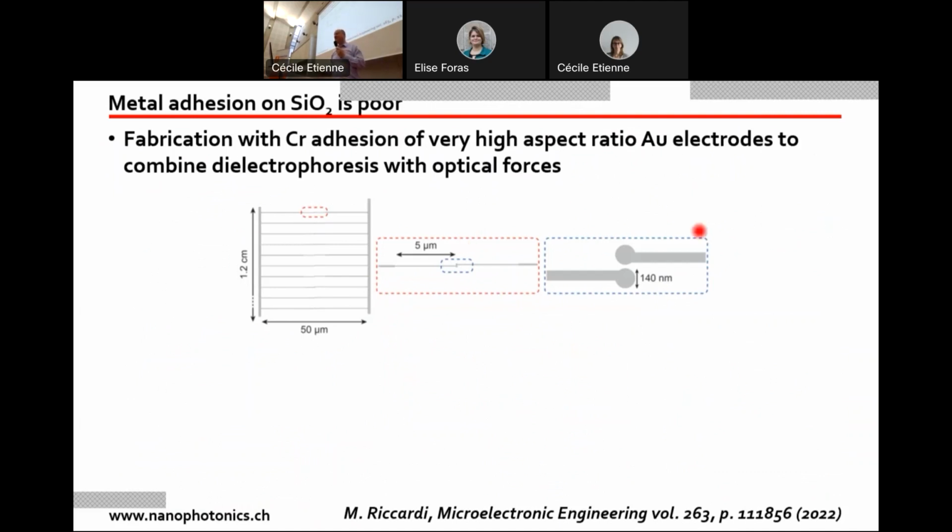So we had here two small nanostructures that look like a small plasmonic antenna. And then we want to connect them over very long distances. This is 140 nanometer. The gap is probably 30 nanometer. So it's very small. But then it's connected over 50 micron so that we can plug in some electrodes here and have some current go through the system.